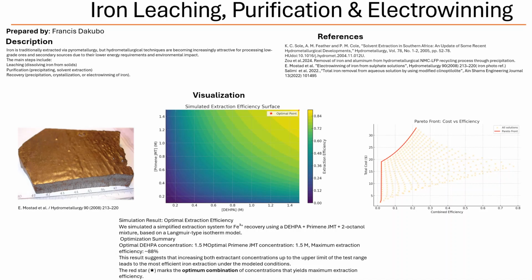They noticed that if the iron concentration in the catholyte got too low, the deposit would crack and peel. Impurities like sulfur and hydrogen sulfide also cause problems, making the deposit rough. Even ferric iron in the catholyte, maybe from a leak in the diaphragm, would mess things up. So purity and process control are key for getting a high-quality product. Exactly. And the analysis showed that they did achieve very low levels of impurities, which is great. Plus, they did it all with reasonable energy consumption, 4.25 kilowatt hours per kilogram of iron.